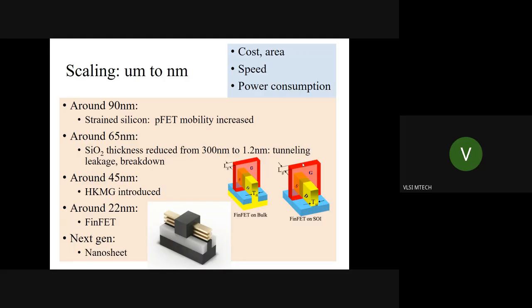Theoretically, if you calculate it out, you will end up with transistors having only a few atoms. We have actually already reached that stage. We are talking about gate lengths of the order of 10, 12 nanometers, and in silicon 0.5 nanometer is approximately the atomic spacing.